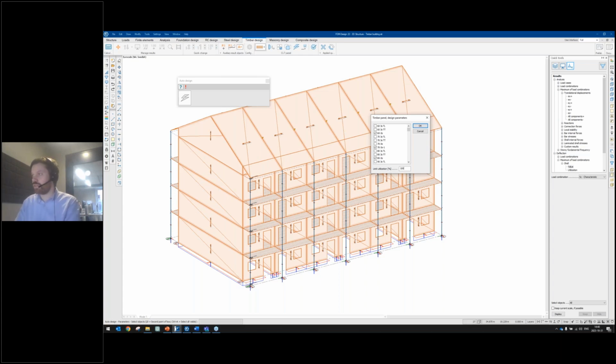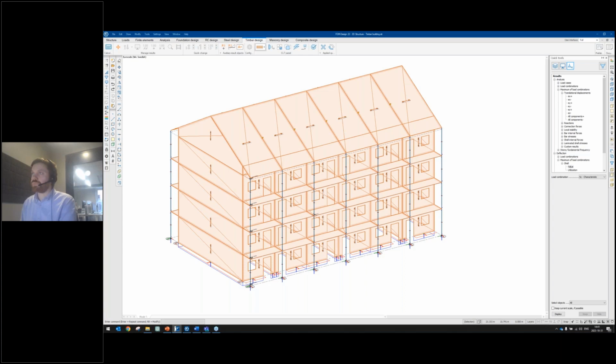If I set this to 100%, I will almost never be able to fulfill the deflection limits as well as the eigenfrequency. So it could be a good tip to set this to 50 or 60% as a starting point to select the initial section, and then you can carry out some additional checks and look at the deflection, and also the eigenfrequency and other SLS checks that you may have to carry out, for example, acceleration and so on.